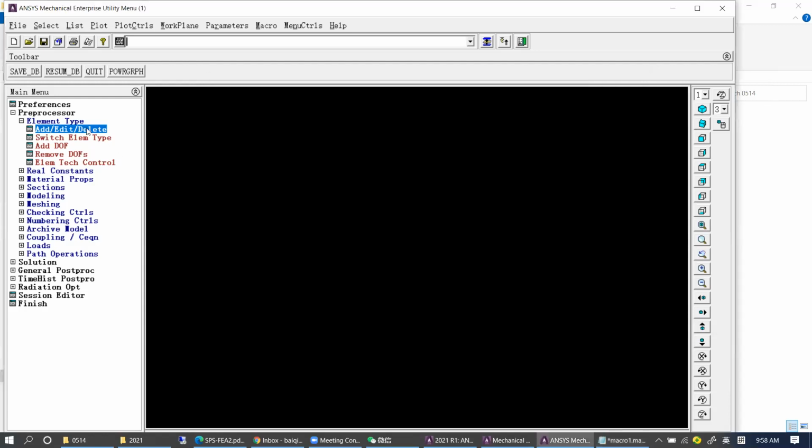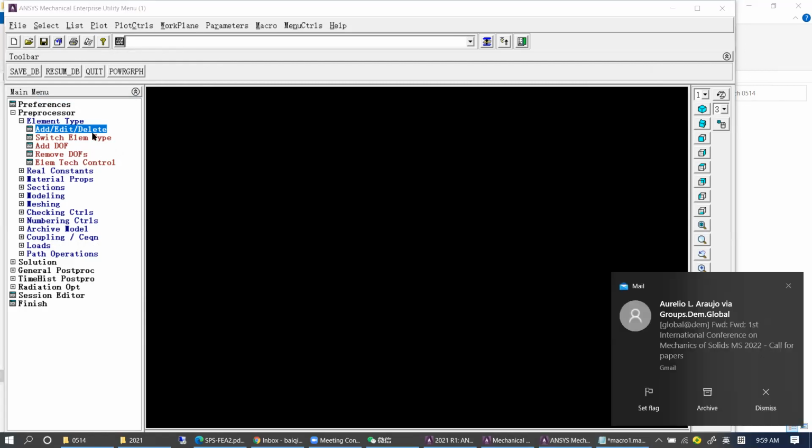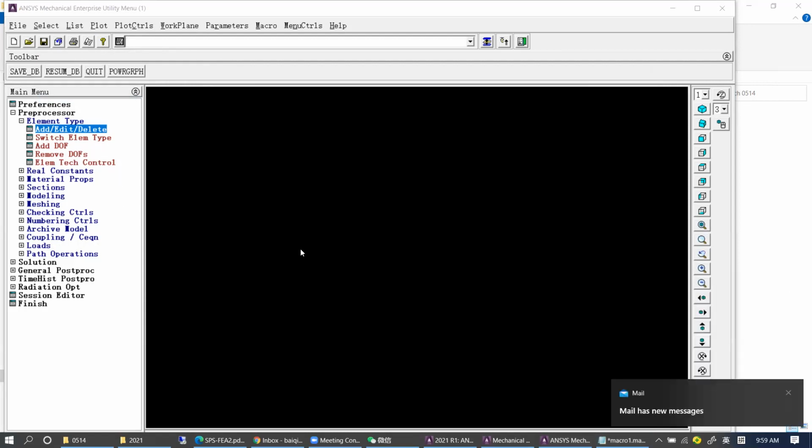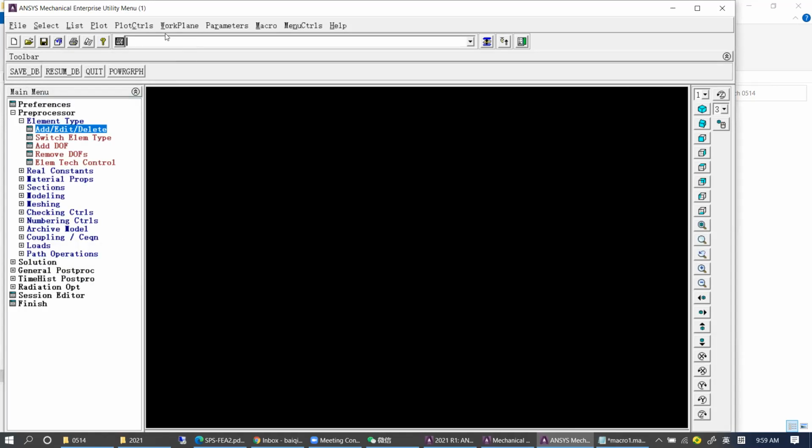And I just showed you how to type there, and we can say ET delete, okay, delete, but not complete delete, it's just DELE. And you can say type 2 and enter. Okay, nothing appears in this main menu, but if you check there, you have only type number 1, because we deleted type number 2 by this ET delete.